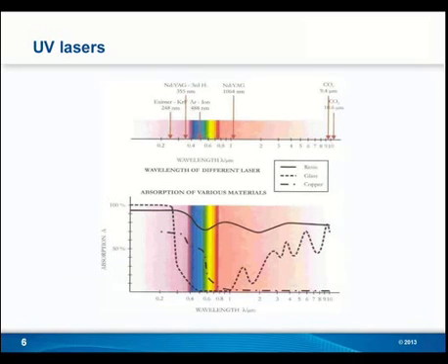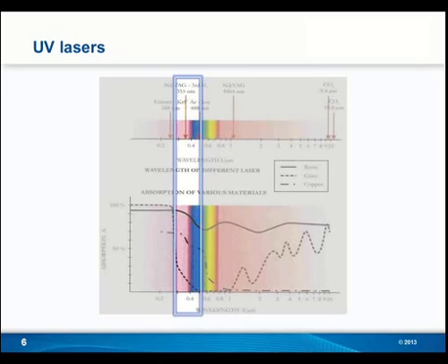If you wanted to compare a UV laser with other lasers, you could take a look at the chart that's now on your screen. This compares the absorption rate of various materials for a variety of lasers. I'm going to highlight the UV laser here. It's a 350 nanometer laser. And you can see the absorption rates for different materials. You can see very high absorption on resin, very good absorption on copper, and even some absorption of glass, which is pretty low for a lot of different lasers.